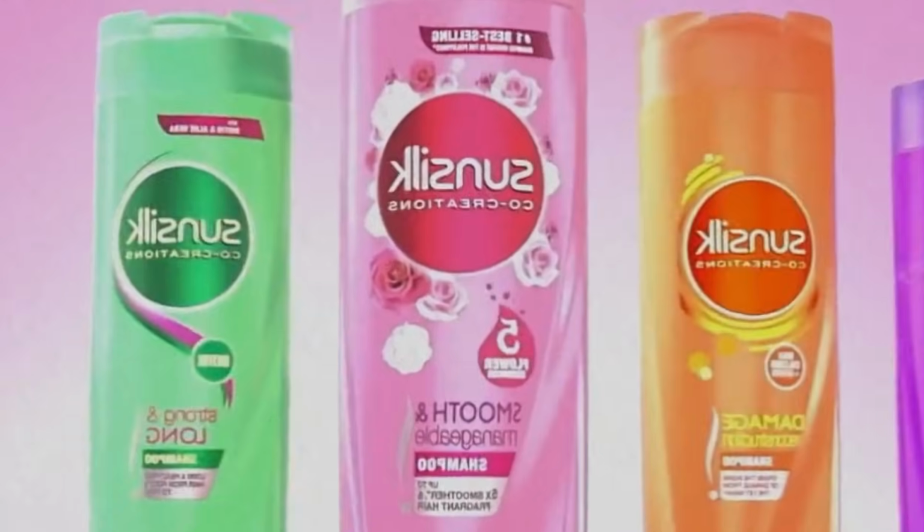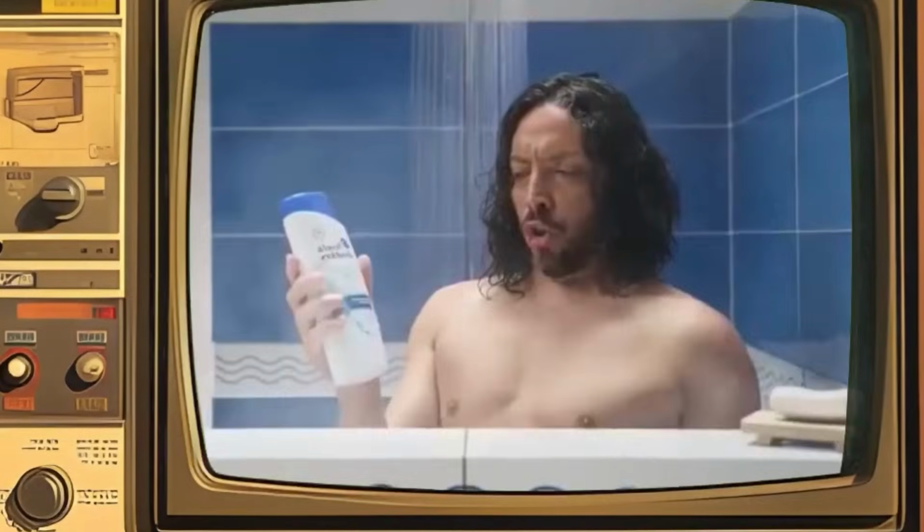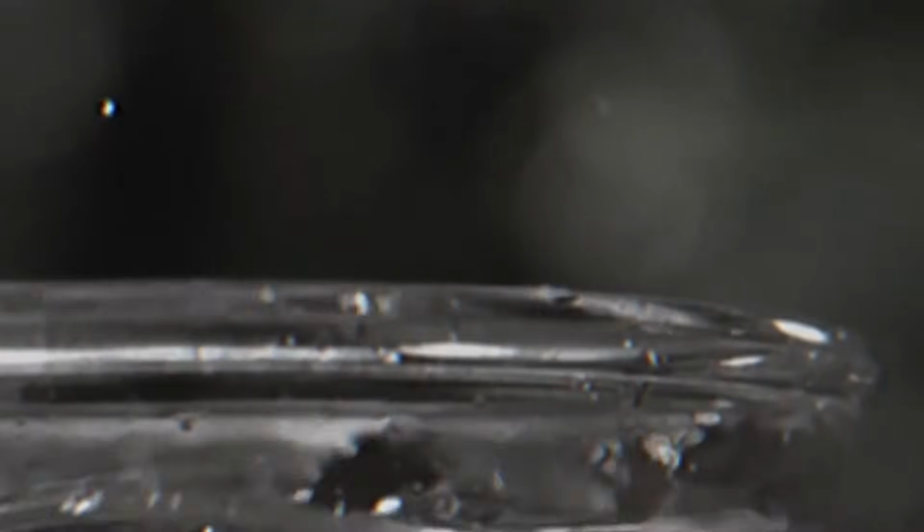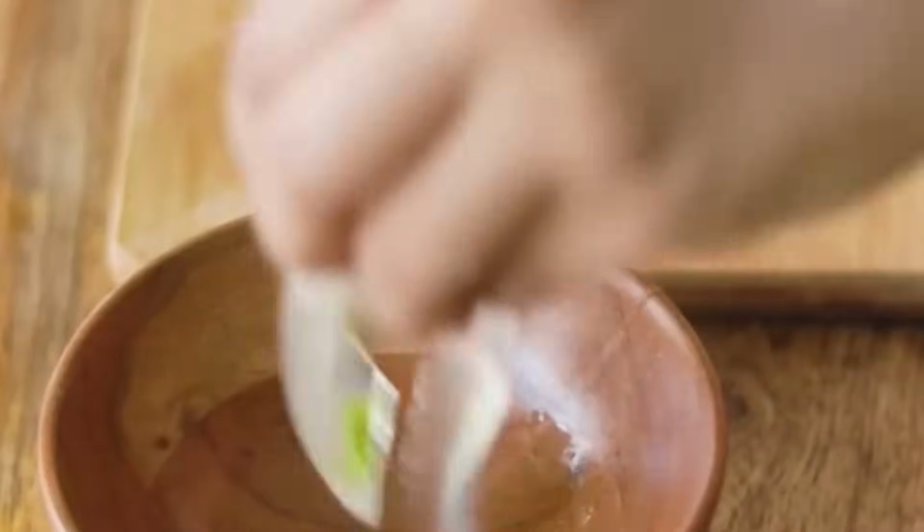These may include phenoxyethanol, sodium benzoate, potassium sorbate, or blended preservative systems. Preservatives are typically added as liquid concentrates and dispersed thoroughly under continuous agitation. The concentration is controlled to achieve microbial stability without affecting product performance.